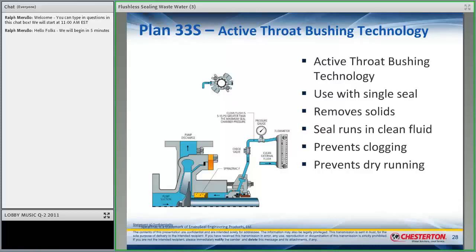The reason is because there is no groove that allows air to be vented from the seal chamber. So you provide a small amount of flush to displace any air around the seal. What you find with split seals is because of the splits, the gas eventually will find its way out. It happens not real quick, but quick enough in many cases.